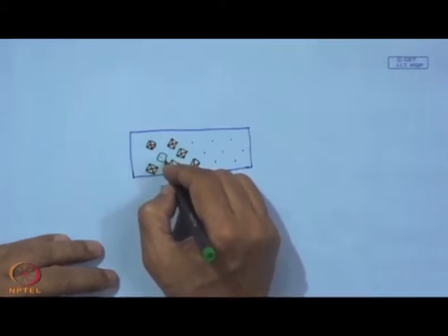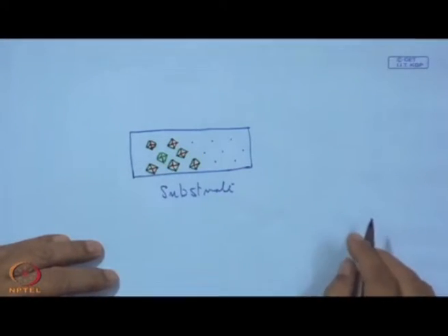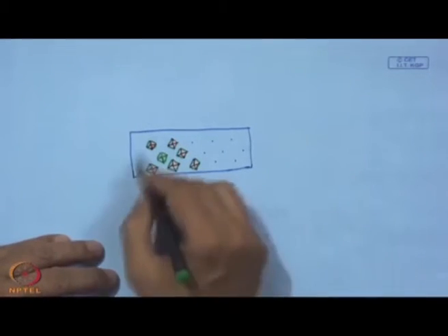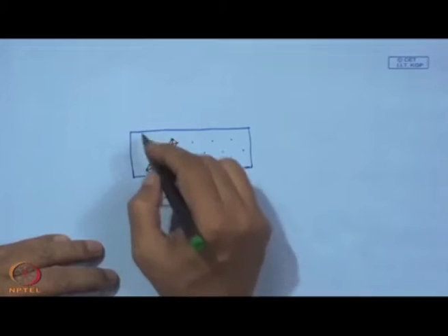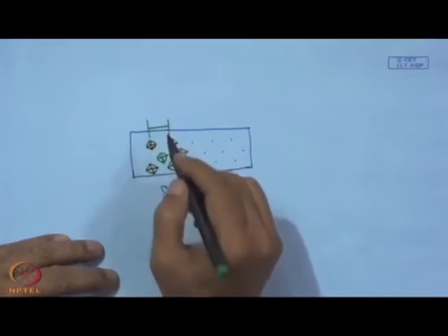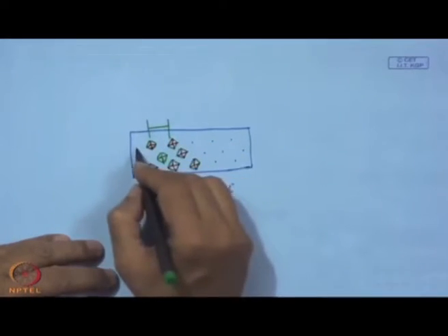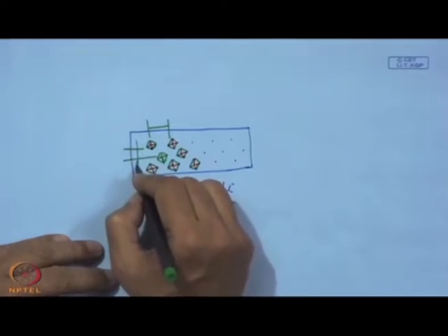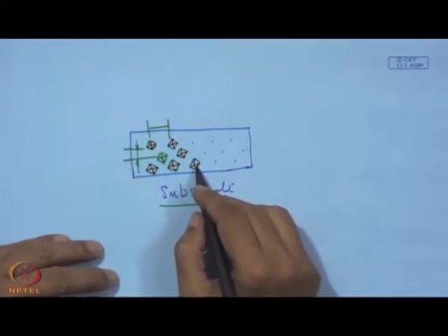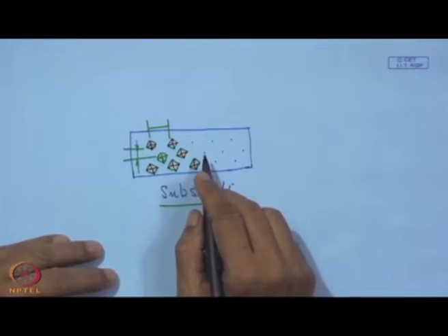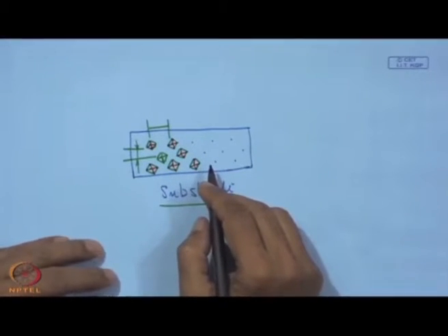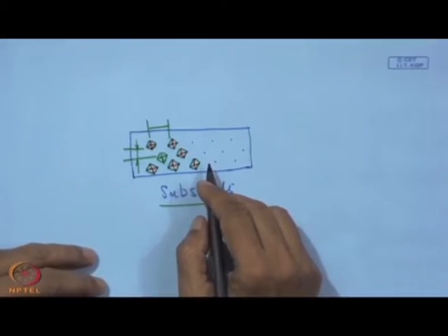So, these are the surfaces, so to say, these are the nucleation sites or nucleation centers where we have this growth of this diamond, and here as usual we can keep this longitudinal pitch, we can also keep transverse pitch, and here this is going to be a tool. So, this diamond can be grown. So, growth of the diamond, that is in the hand of the operator of the CVD.